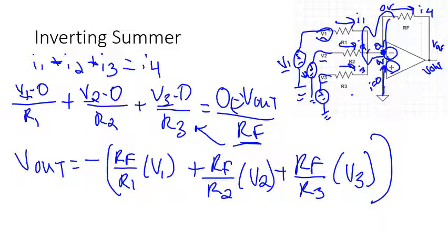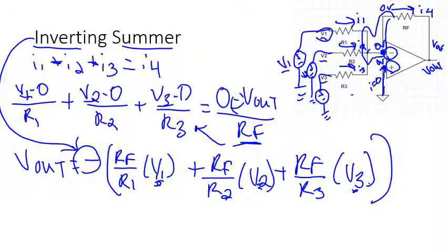input. What did this guy do? Well, he took several different voltages, V1, V2, V3, he multiplies by a factor and inverts by the sign from it. So it's called an inverting summer. Inverting because my sign flips from my voltages and my inputs, V1, V2, and V3. I have multiple inputs here, and it sums V1 plus V2 plus V3.